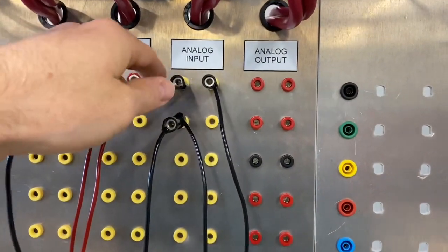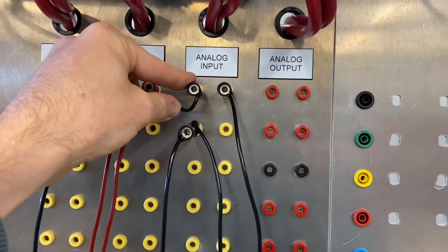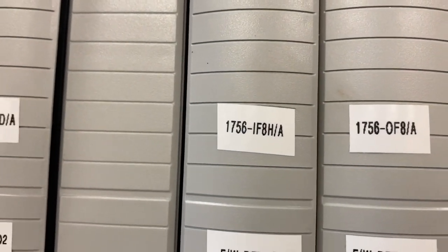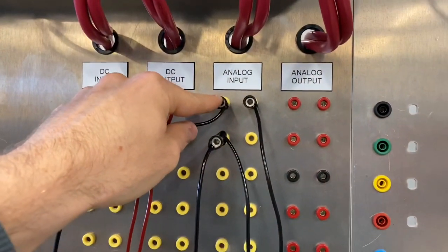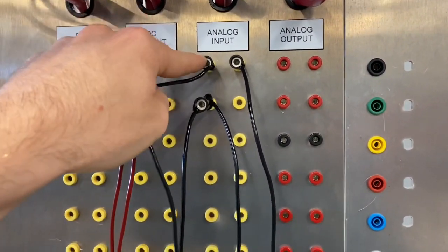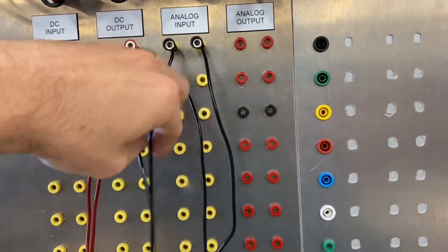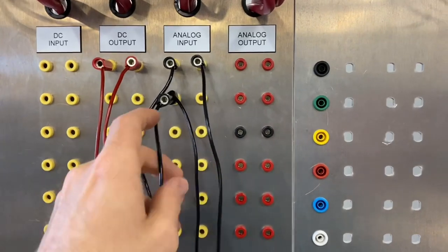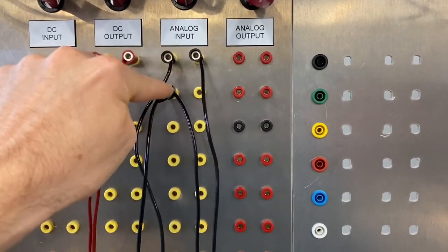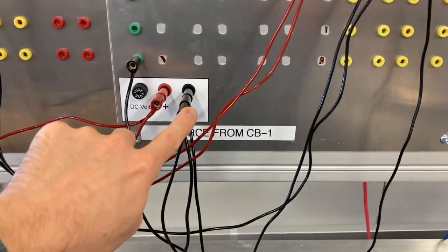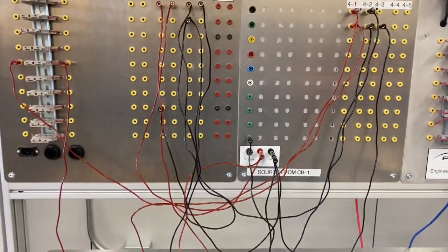And if we look at the wiring diagram for our analog input card, our 1756 IF8H module, we would see this is wired correctly. So this is the transmitter, the negative of the transmitter coming in, and since we're using current of 4 to 20 milliamp, we need to put a jumper from these two terminals, and then we run down and over to the negative of our power supply. So if you look at the manual, you could follow all my wiring.